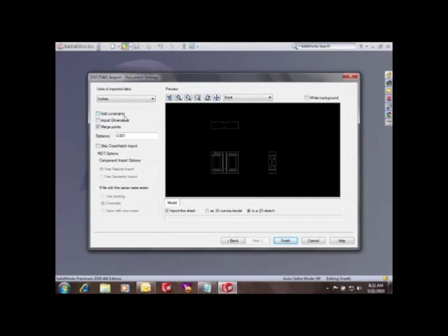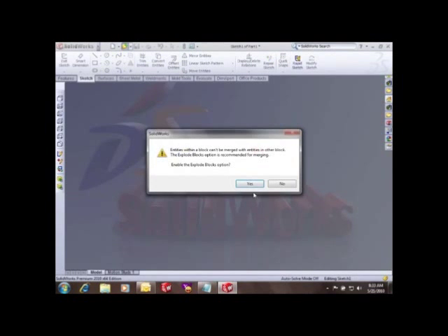On this screen you can see that I can add constraints, so perpendicular, parallel, equal, horizontal, vertical, constraints like that in SolidWorks sketches can be added automatically. I can also import the dimensions directly from the 2D file if I want to. And we can also let SolidWorks clean up the sketch a little bit here by setting a distance that it's going to search around points, and if there are lines with endpoints close together, it will actually pull those together to create closed contours. We can import the 3D model. If the AutoCAD file has 3D information in it, we can bring that in. In this case, I'm going to import just the 2D sketch and show you some of the tools that we can use to help generate a 3D model.